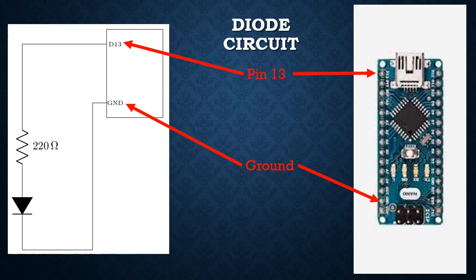It'd be hard for me to show you the board, but I'm trying to give examples of how you could make this work. So the example that I used, we'd go from D13, just to the left of it, to row 22, to row 24, row 24 to row 25, and then row 25 back up to ground.